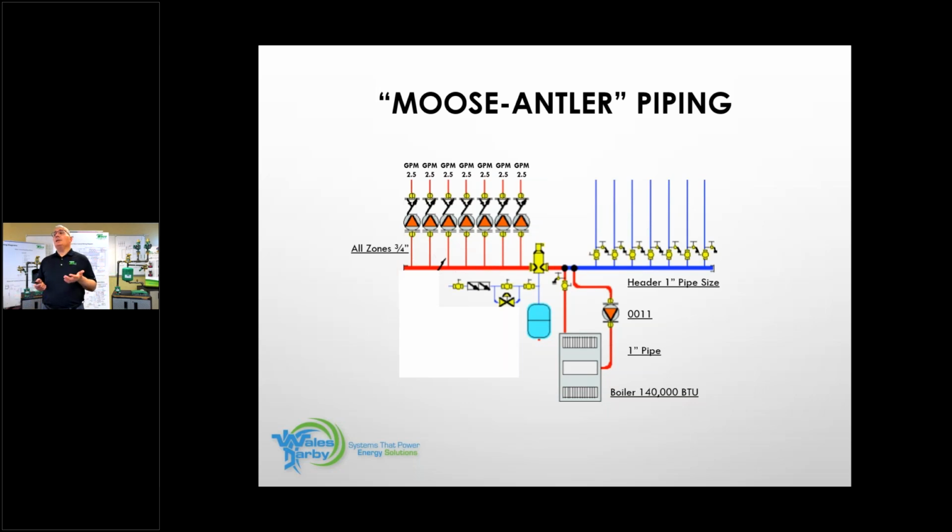Okay. If it's over pumping, if it was an undersized boiler and I need to move 175, is that supply header and that boiler piping right? I need to move 17.5 GPM. Can you move that through 1-inch pipe? Look at your charts. Can we do that? I don't think so. So the piping would have to be changed.